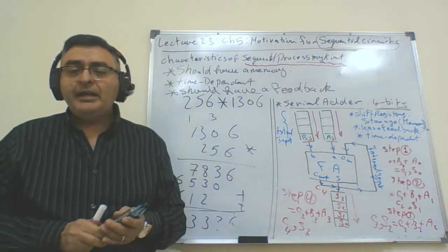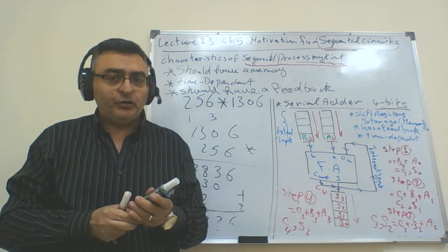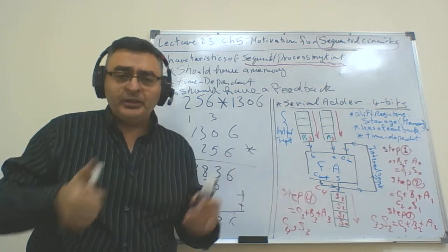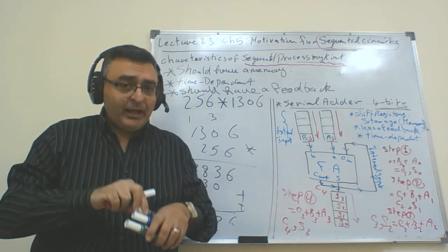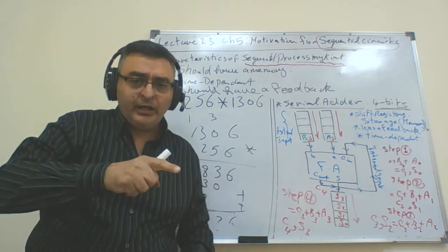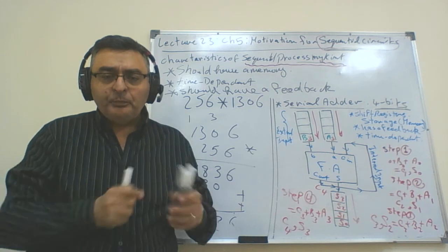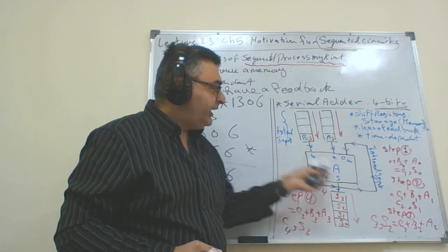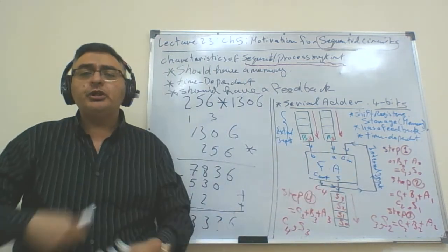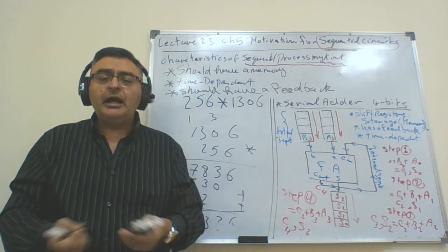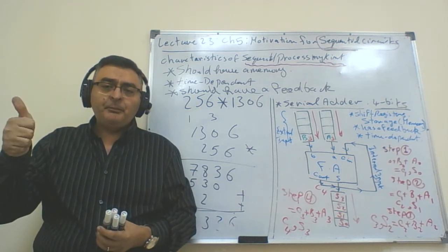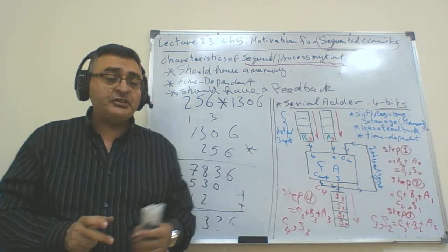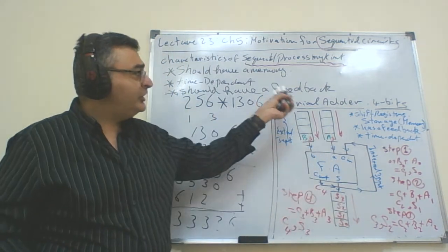So this new system is different from the system that we have built before. It's different in 3 regards. It has a memory to store the inputs and the outputs. It has a feedback, the output of the system connected to the input of the system. The output of the system is not fixed. It depends on external inputs and internal inputs to produce each time a different output. So the system is time dependent, has a storage or memory, and has a feedback. If the system has these 3 characteristics, we call this a sequential circuit.